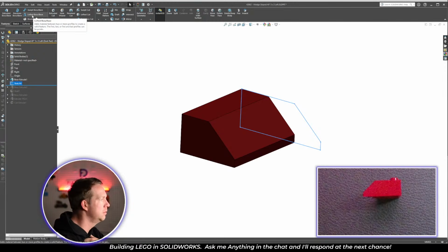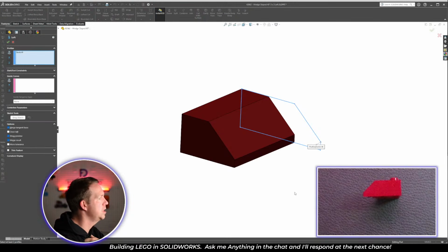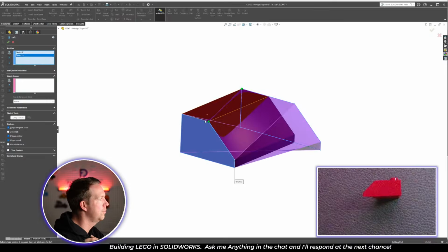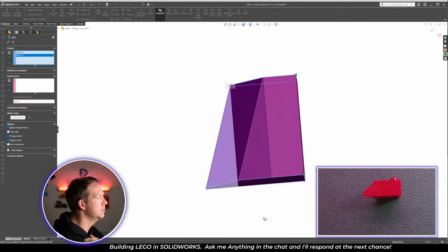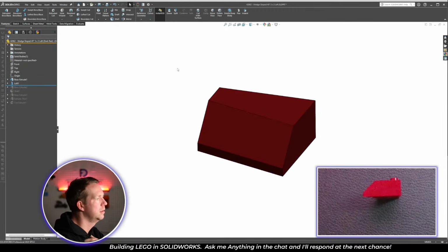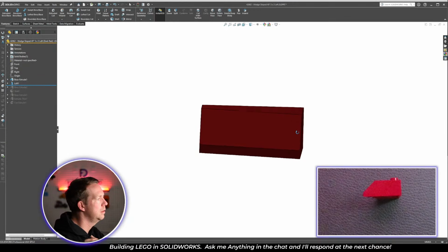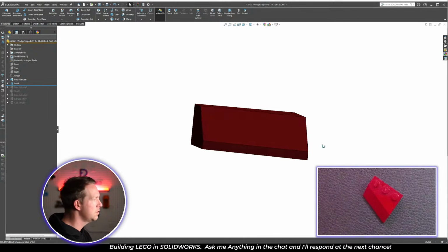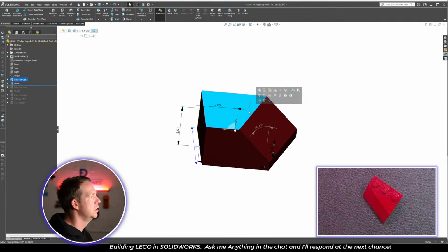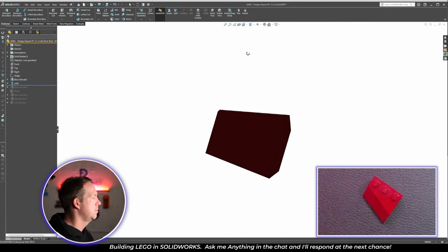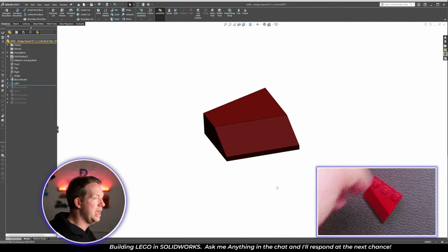So with that sketch profile selected, I'm going to click the other profile here. I'm just going to move the connectors. And there we have our new lofted feature. And we press OK. And now I think we've got a correct form for the part. So loft is a very good solution here. All the faces still remain flat, which is good.